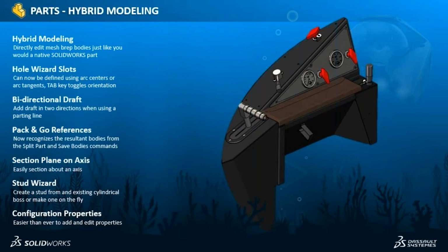The stud wizard is another one. Kind of what took so long, right? We all build these types of features. We're all using studs and tapped bolts like that. They hold a lot of our parts together. So this was a big one for a lot of our user base. The stud wizard is basically like the Hole Wizard, right? We now don't have to go through and define that entire stud and the shoulder lengths and everything that takes place on it. It's built into a nice wizard. And you'll see in the demonstration that basically drawing a cylinder these days can get you a pretty fancy stud that's really detailed the way you want it.